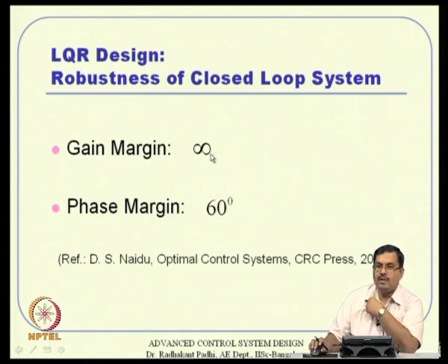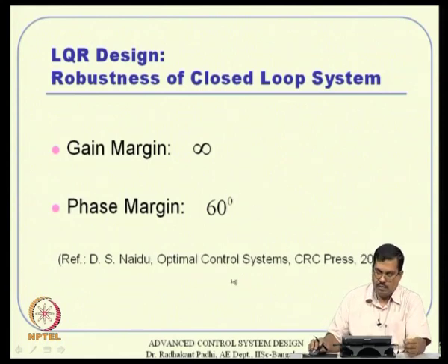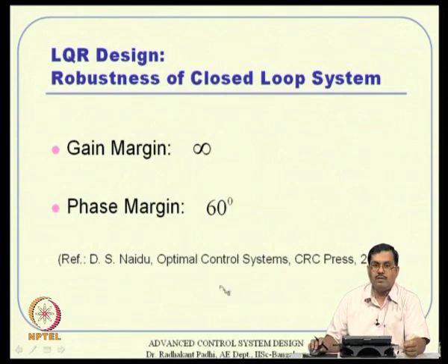That means LQG design turns out to be LQR design with Kalman filter based state estimation, and LTR is something called loop transfer recovery. Okay, so, those are concepts that are available from the linear quadratic design details. Those of you who are interested can see some appropriate book. One such book is certainly this book, you can also see details of that here.